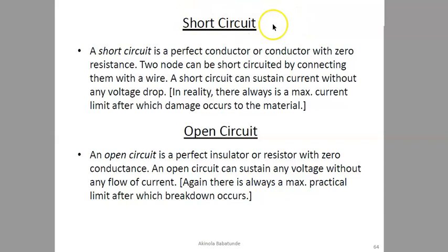Remember, when we have a short circuit current, the voltage is zero. When we have an open circuit voltage, the current is zero. Open circuit voltage simply means that current is not allowed to pass through the terminals. So we have maximum voltage, current is zero. For the I short circuit, we have the maximum current possible. A short circuit works as a perfect conductor. It conducts as much current as possible. It allows as much current as possible to pass through the terminals. So in this particular case, we have I short circuit but zero voltage. Please pay attention to this. It is important. This is where we are going to stop for today's lesson.